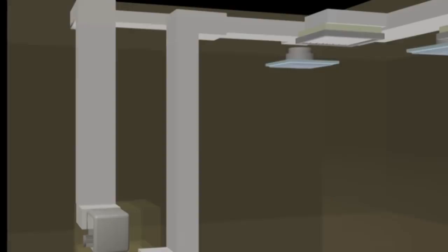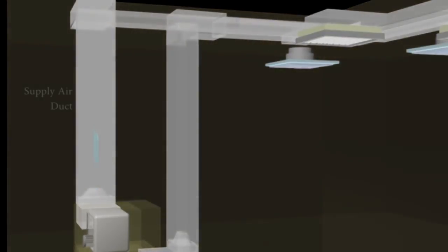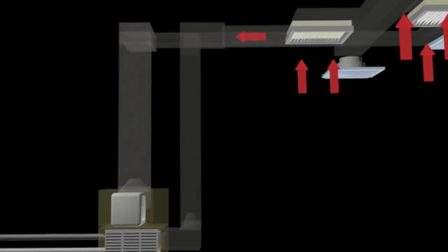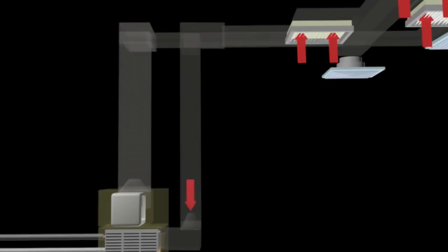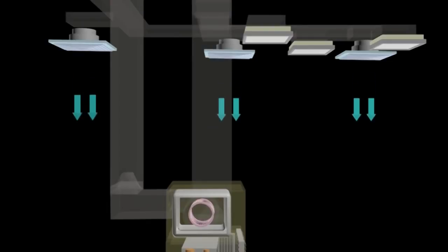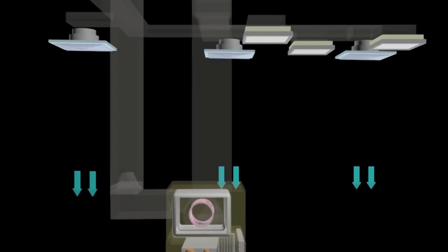The channel that the air flows through is called ducting. There are two types of air duct, which are the supply air duct and the return air duct. These air ducts are coated with insulating material consisting of fiberglass wrapped with aluminium foil. It reduces heat transfer from the environment to the air duct. Air returning to the air handling unit will pass through the filter before passing through the cooling coil and returning back to the room. This ensures that the air returned into the room is clean.